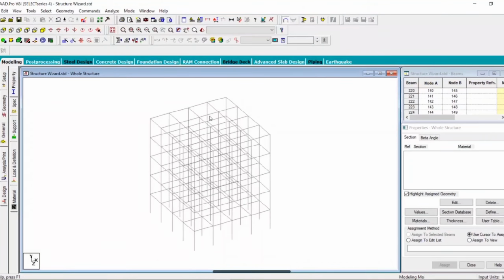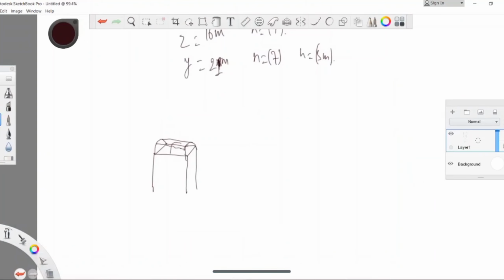Now we will place a truss on the top of this. For that, you have to remember that if this is your frame, and suppose that this is the front view of a frame, then you make sure that the vertical members that you got of the truss, they lie perfectly on the columns, so that the load is transferred accurately to the columns and the beam don't take much of the load.